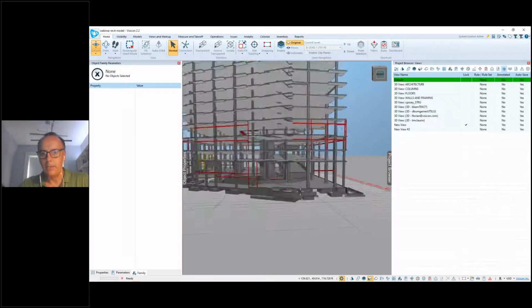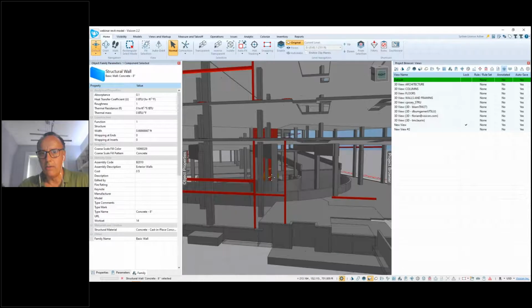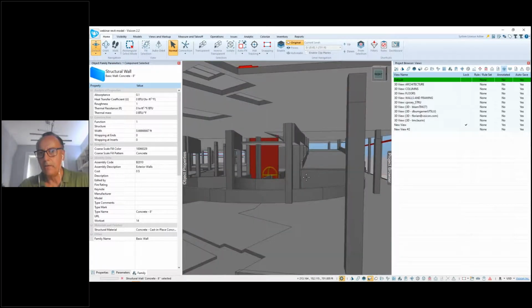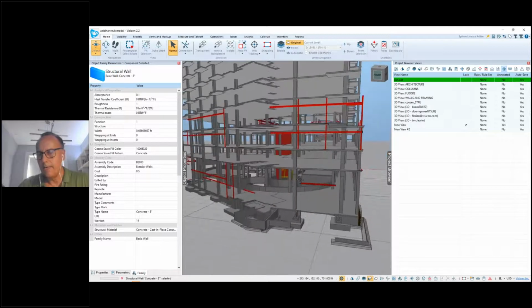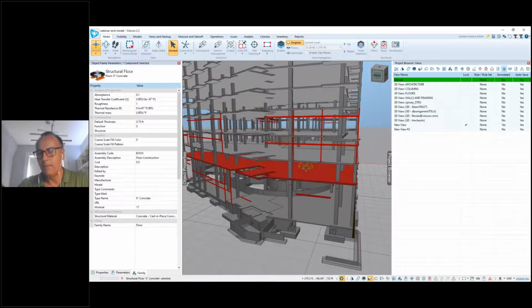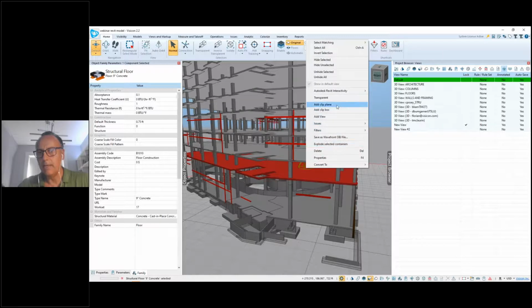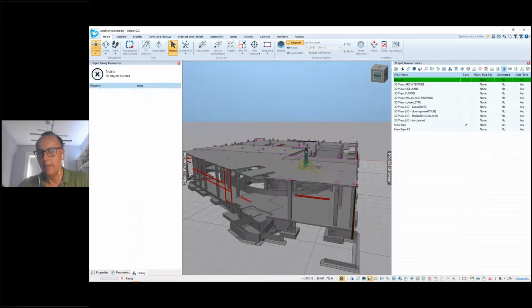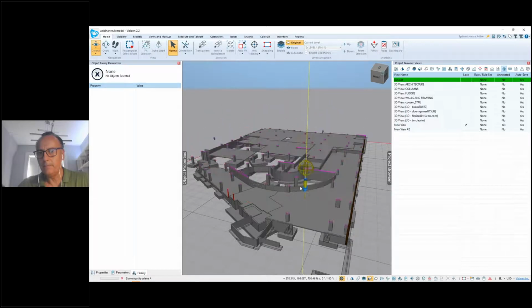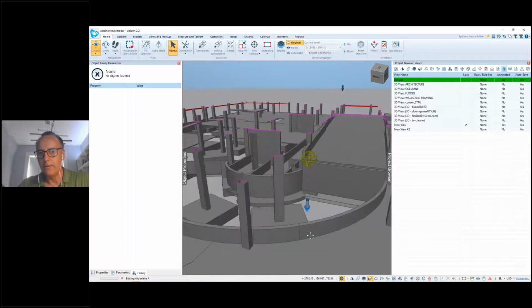And in this particular project, I'm working on some lower level coordination. You see, we had all these transfer slabs and we have all these ramps. I want to understand how the various levels are connected. So I just simply tap on the top of a component or any face, right click, add a clip plane. See that? Add clip plane. This allows me to very easily come in and be very detailed about coordinating and understanding, right?